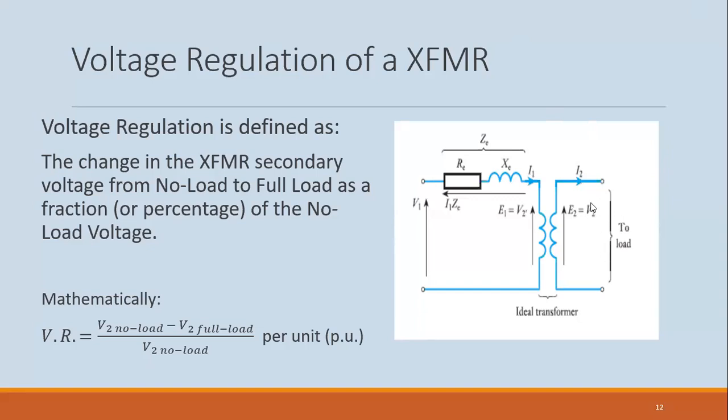I put a load on the transformer, the voltage will change. So if it is a lagging power factor load, the voltage will actually decrease, right? At the terminals here, right? So just loading is going to bring down the voltage, especially for a lagging power factor load, right?